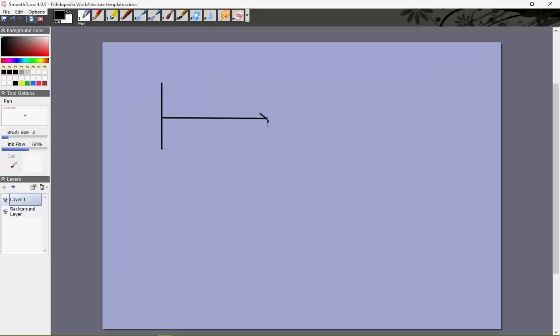So in an LCR circuit, you will have R here, you will have XL here, you will have XC here. So what will the sum be? We'll just for a second assume that XC is greater than XL. And I'm sure you'll be able to deduce what will happen if XC is less than XL. If XC is greater than XL, let me just draw it bigger like this. This whole will be XC, this is XL. So this much might be XC minus XL, right? And if you add this like this, then it will go here, this will be Z, this will be phi.